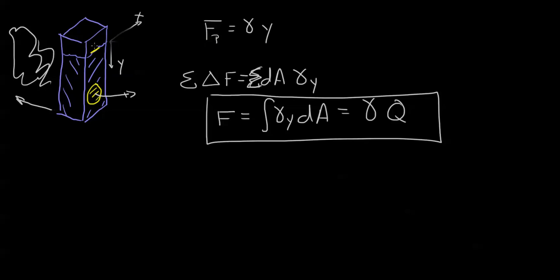In order to find where the force is acting, we're going to try to find the moment about this hinge. The moment about the hinge is the sum of lots of small moments, right? The only place that we have those small moments is right down here. So the small moments are simply the y value times whatever the small force is at each of these small areas.